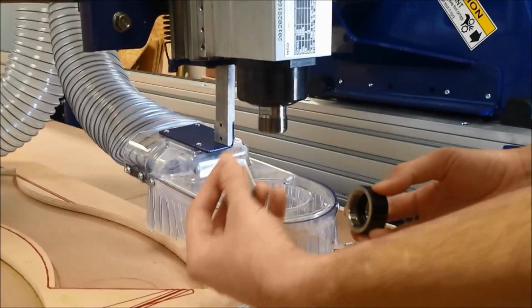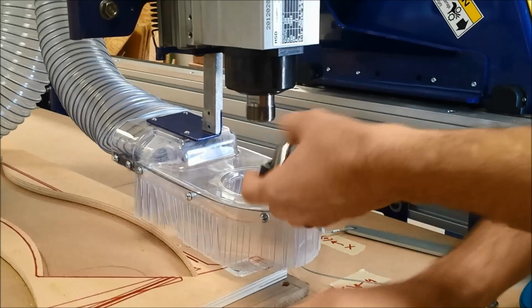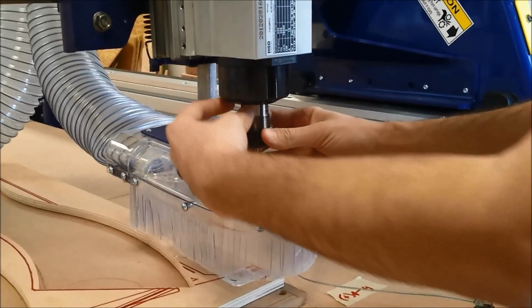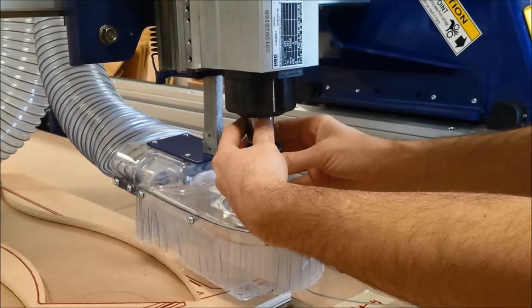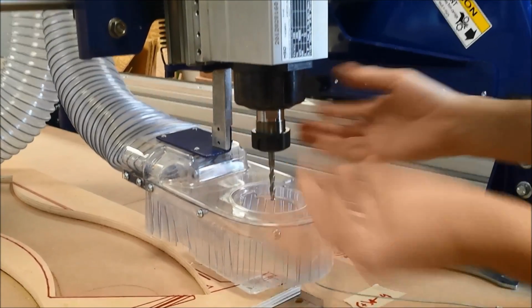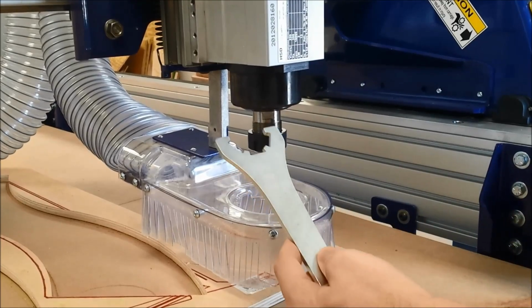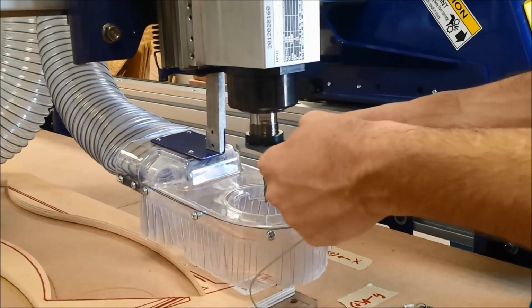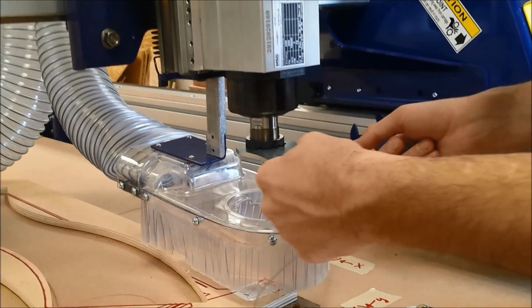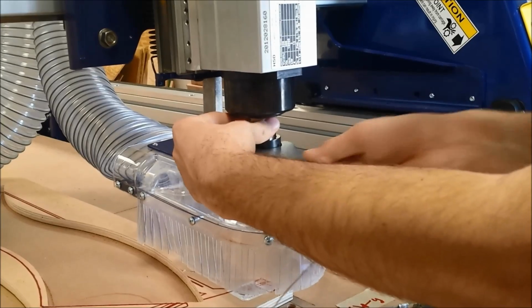and we're going to put the collet in like this, and then it gets supported inside like that. And of course our drill bit can go inside that. So we just start this. Be sure to support all of this as you're doing it. So we start that until it's just a little snug, and then we take our tools and tighten it. So this wrench, actually you can't grab it like a normal wrench here. We have to go under it and go up, and the teeth lock and it will not come off. So that's useful.